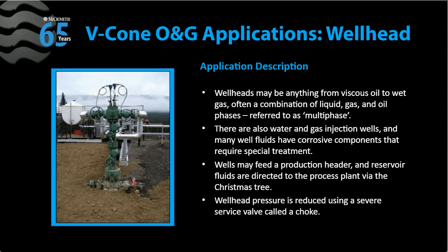There are also some wellheads where they are using water or gas injection, and many of the well fluids have corrosive components that require special treatment. And wells may feed a production header, and the reservoir fluids are directed to the process plant via a Christmas tree, which is what you are seeing in the picture next to the text.